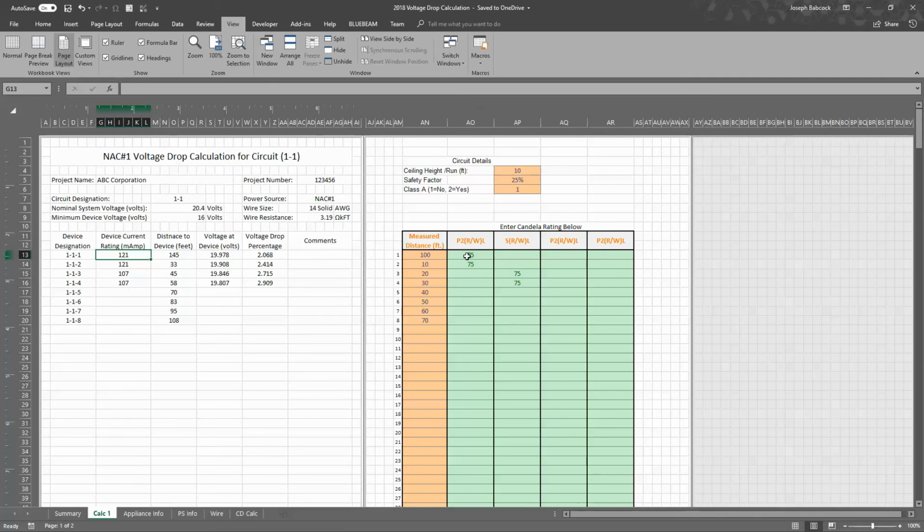submittals. So to just do a rough current draw calculation here, I'll start out with a 15 candela, and I'll step through all of the candela ranges and show you as I go through: a 75 candela device, a 75 candela device. So this will be 110 candela horn strobe and 110 candela strobe.